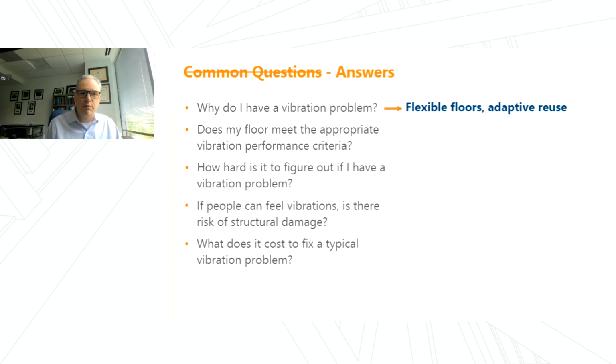Does my floor meet the vibration criteria? Yeah, so it depends on the use. If you have people complaining, it's a good sign performance isn't acceptable for human perception and office workers. For sensitive equipment like imaging machines or microscopes, measurement-based evaluation is essential. You can't really rely on your feel for the data in most cases there.